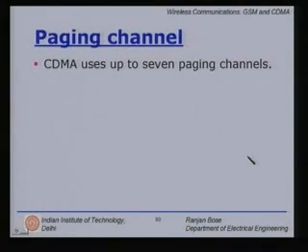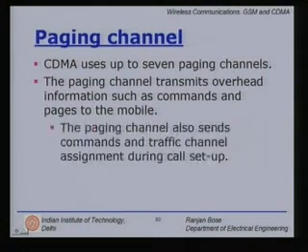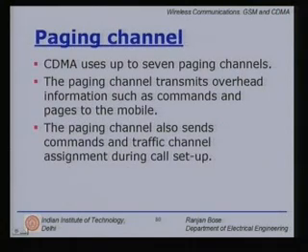Paging channel, as the name suggests, is used for paging a mobile. CDMA uses up to 7 paging channels. The paging channel transmits overhead information such as commands and pages to the mobile. The paging channel also sends commands and traffic channel assignment during call setup. So, each time we are talking about handover, this call setup must be initiated.